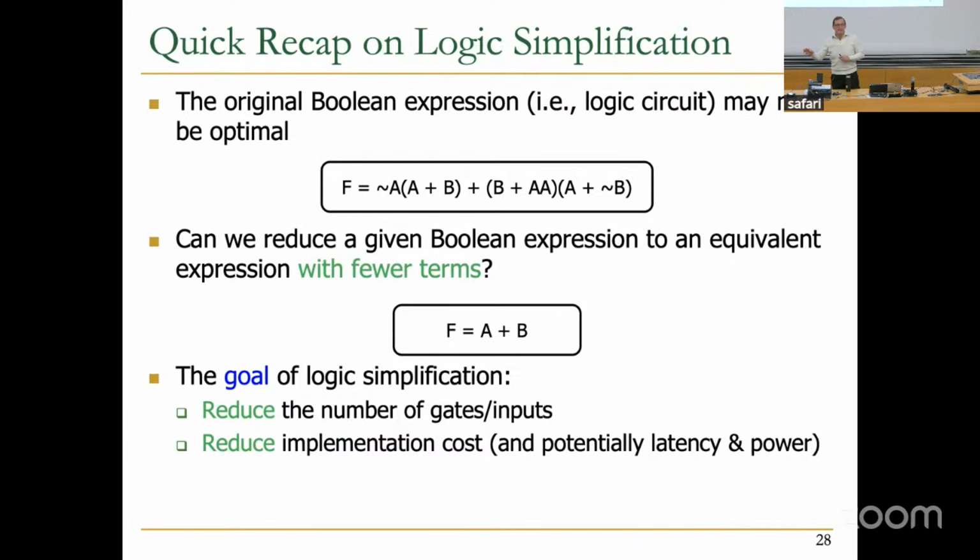The goal of the design automation tool, or if you don't have that tool, the goal of the human doing that mapping, is to figure out a mapping from a high-level Boolean equation to a really nice implementation that satisfies some goal. The goal may be lowest power, highest performance, lowest latency, lowest area, or a combination of all of those. You can see that the design space can be huge. So in general, minimizing logic is good. But when mapping the minimized logic to the underlying gates, sometimes you may not want the completely minimal one, but a little bit less minimal logic that maps to better gates. It's good to think about that.